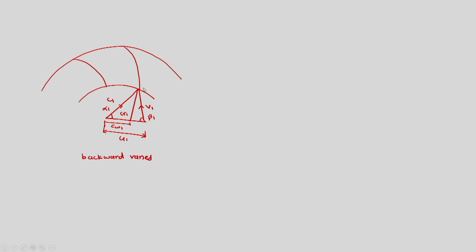So this is the velocity triangle at the inlet, and at the outlet the velocity triangle will be this way, where this tangentially would go out as V2 velocity. This tangent to the circle will be the tangential velocity, which is U2. So this complete is U2.